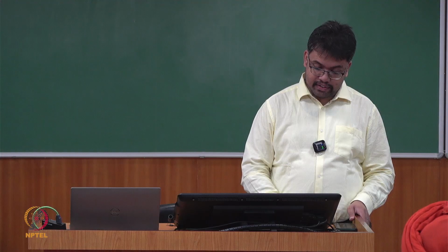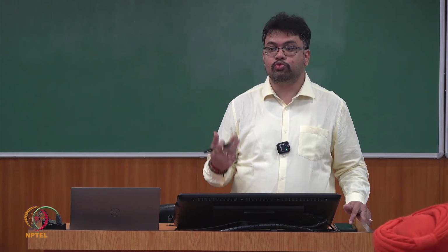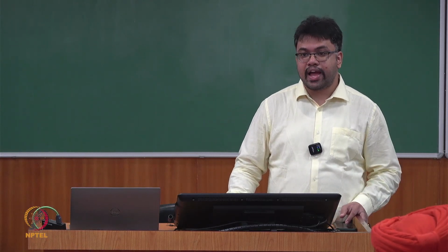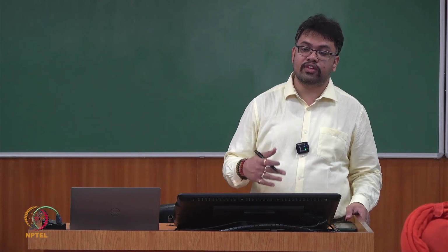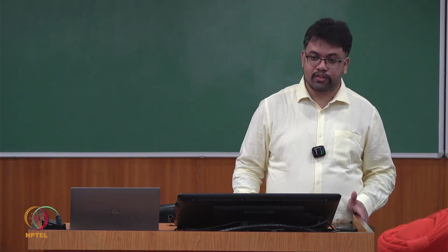So that we have seen. And after that, we introduced the state vector, what the state vector is, and how from the state vector we can solve for the natural frequencies of a particular system, of a particular beam. That is important because in the case of a bar, we have a 2x2 matrix that can be easily solved. But once we are talking about a beam, it is 4x4. Now if we go to a further complicated structure, then it will become very difficult to see how we are going to solve it. So that is one problem.